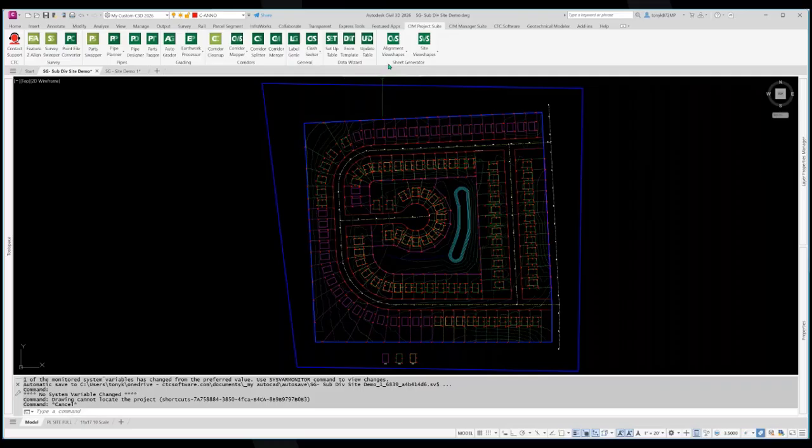So it does have a few requirements. It's right here on your toolbar, as you saw from the PowerPoint. And I mentioned it's a top to bottom. So we need to create our site view shapes. Then we will create our layouts. And if you make changes, you can just update those. Those will write directly to your sheet set manager. If you're doing them in the drawing, you'll just recreate them.